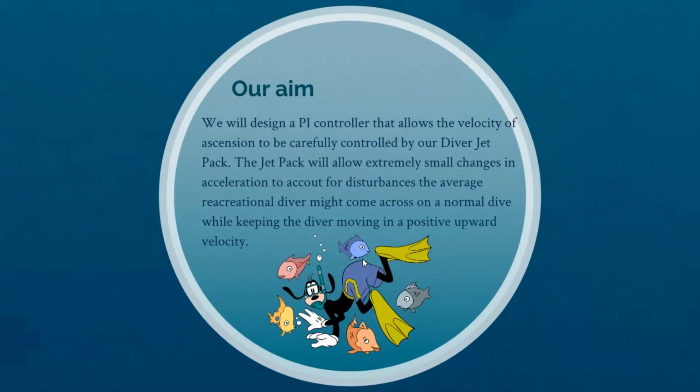So our aim is to design and simulate a PI controller that allows us to set the velocity of the ascension and to be carefully controlled by this diver's jetpack. The jetpack will allow extremely small changes in velocity and acceleration to account for various disturbances that the diver can experience during a recreational scuba dive.